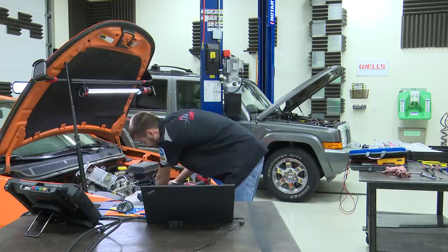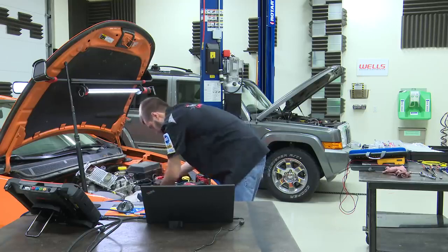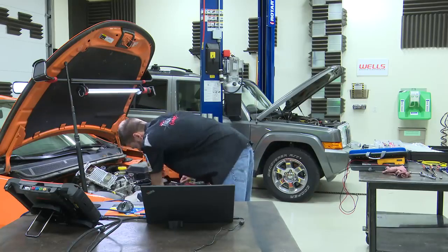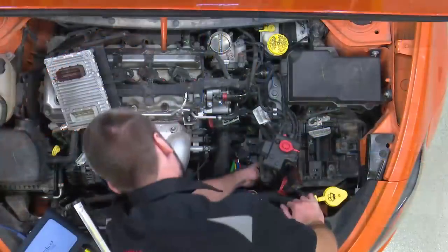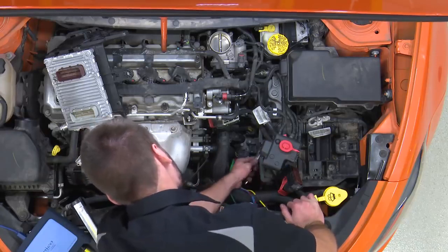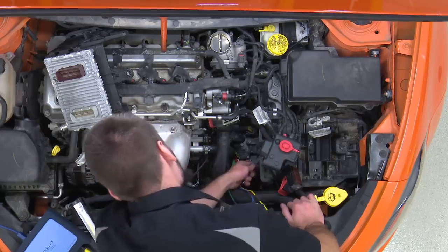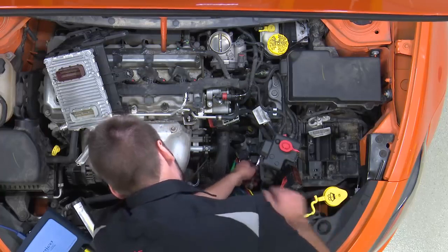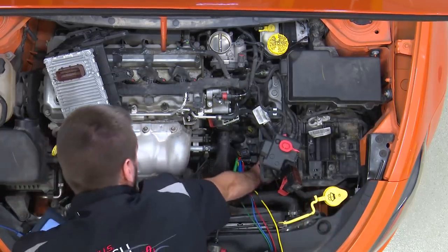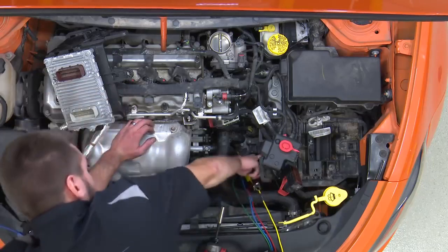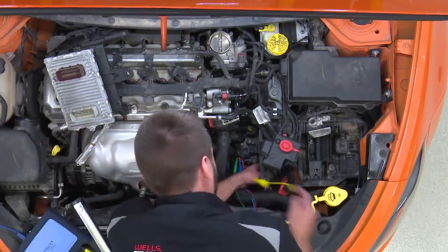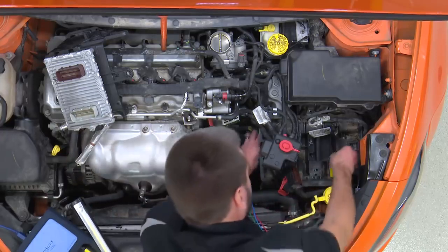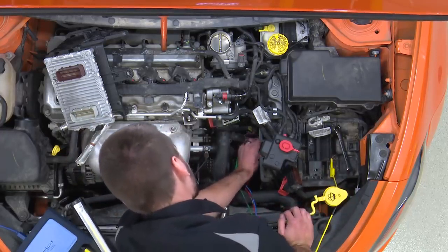I believe you're supposed to remove the battery tray to get this out, but I think we can do it without. All right, so I'm just breaking the nut loose that's holding our shifter cable to the top of our range switch. And this would be 100 times easier with the battery tray not in here. But again, you got to go through the wheel well to take a couple bolts out. And I just unhooked one of my scope leads. Well, if anything, guys, today I'm demonstrating the struggle of fixing cars.